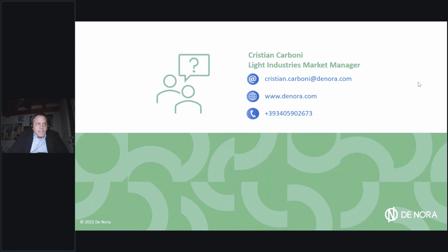That's a good question. It depends on regulation, from country to country, and also on the food application, but let's stay on safety. Normally, when a company uses ozone in a storage room, they have a signal, a red light or other signals outside the storage room that say please don't enter if the red light is on. There are also safety measures, for example, if people open a door, the ozone turns off, and so on.